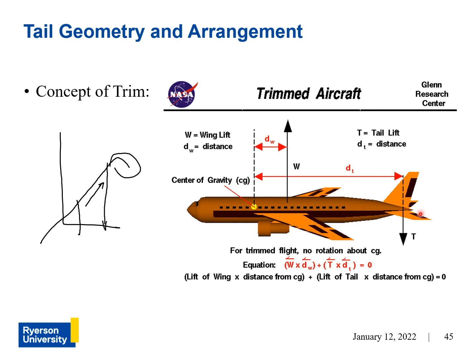So an aft horizontal tail typically has a negative incidence angle for that reason that I explained earlier, which will produce a downward lift force to balance the wing body pitching moment. So actually, if I were to draw this, since the angle of attack / incidence angle would be negative, here the lift will actually be a negative value.